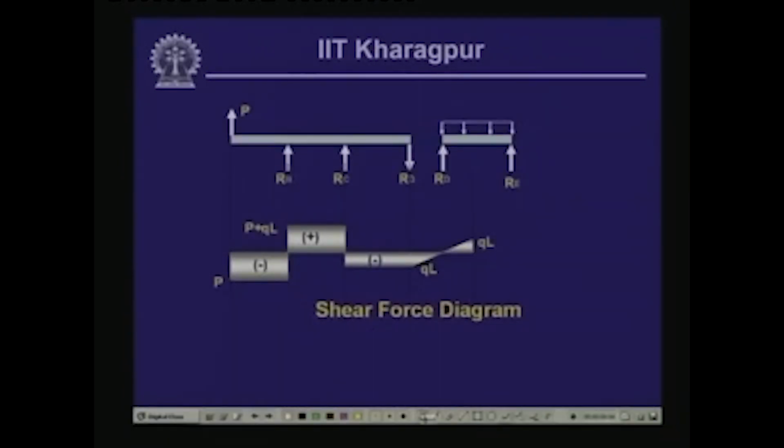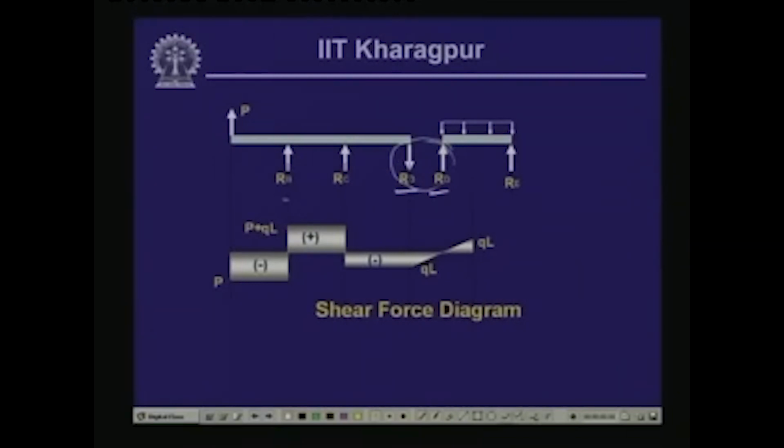Now, this is the diagram plotted, but you see that this particular beam has been split at the articulation, and we have introduced one reactive force RD over here. Please note that these 2 forces are balancing in nature. That means one beam is getting supported over the other and transferring the shear force here. So, it can resist the shear force, but it rotates when it comes to bending. Now, the uniformly distributed load acting over here is Q, this has a length 2L, and all these segmental lengths are L.